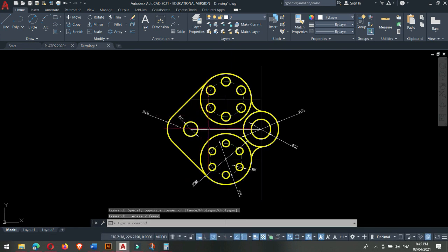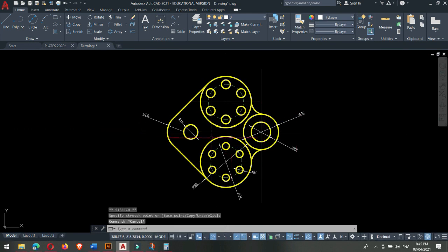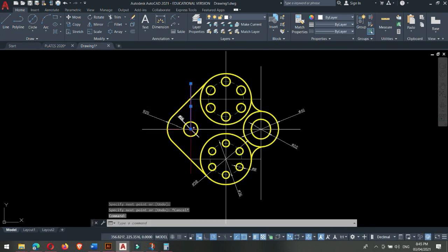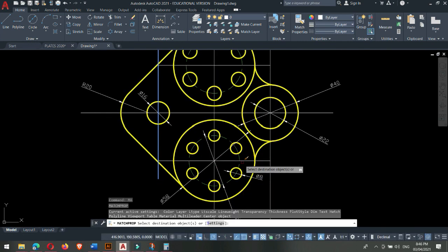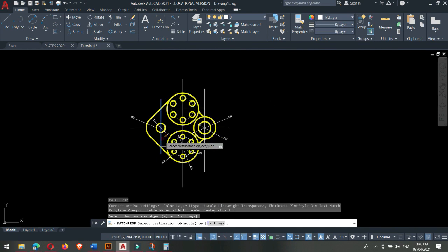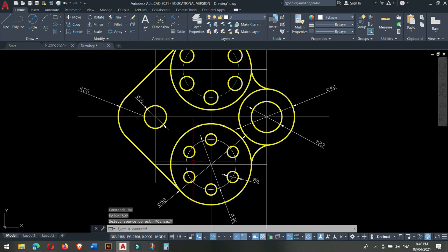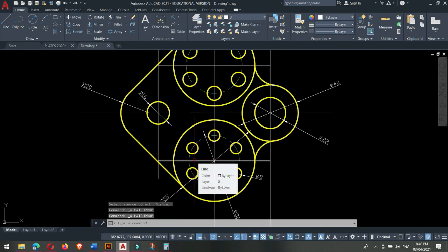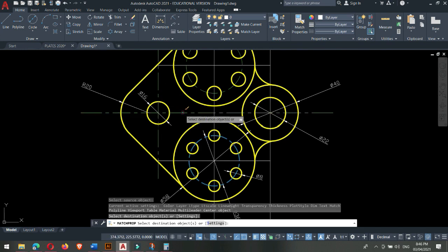Okay, you can also extend a line using these points. You can see down here. Okay, so those are the center points. I'm also going to create a line here and extend it downwards. And I'm going to use Match Properties again. Match Properties, MA on the keyboard. Left click here and click all the center lines. Control Z or undo. And it follows. Alright.